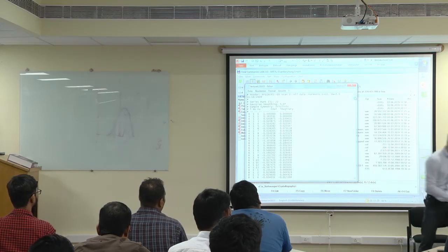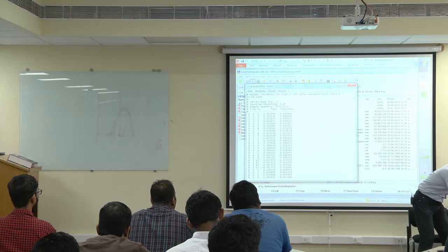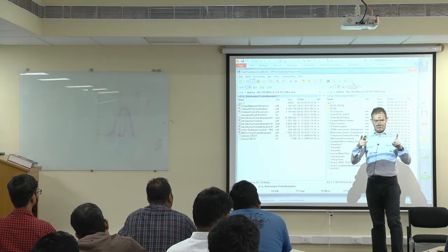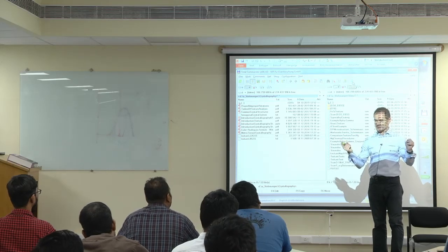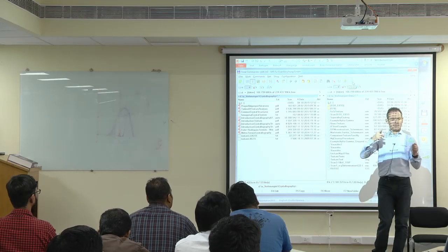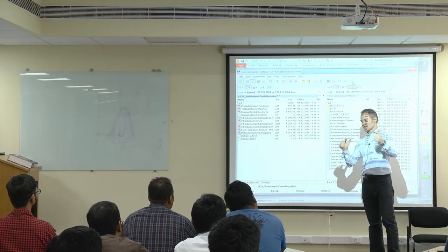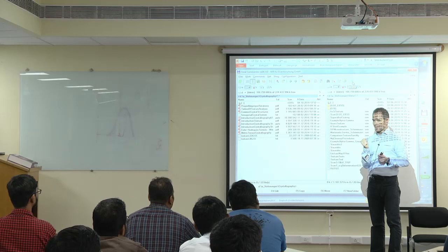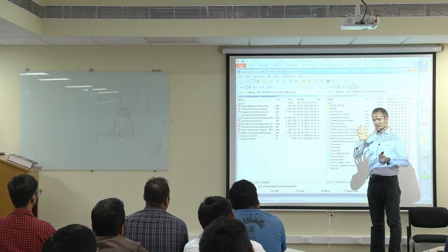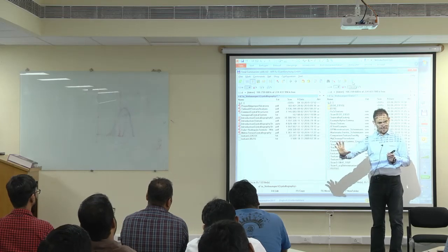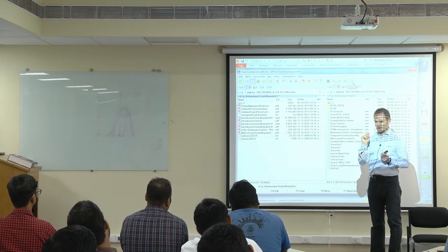And of course, very important is you must make sure that you have sufficient input data. If you measure only 2 points, then it's not reasonable to calculate a texture which contains 400 descriptions. There's a rule of thumb, and I can recommend you to read one of our papers as well. A rule of thumb was that you need about 1,000 orientation measurements, well distributed over your sample, to have a reasonable idea of texture.